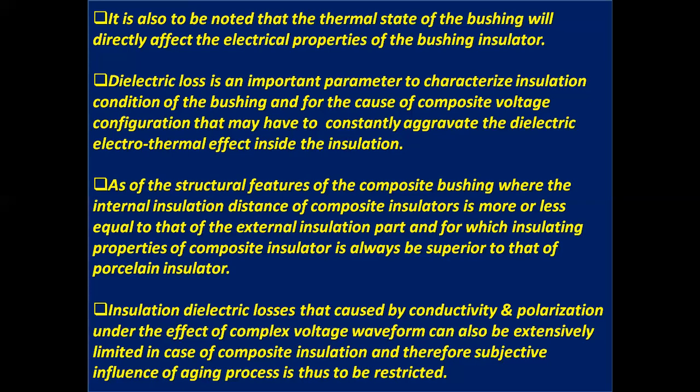As of the structural features of the composite bushing, the internal insulation distance of composite insulators is more or less equal to that of the external insulation part, for which the insulating properties of composite insulator are always superior to that of porcelain insulator. Insulation dielectric losses caused by conductivity and polarization under the effect of complex voltage waveform can also be extensively limited in case of composite insulation, and therefore the influence of aging process is restricted.